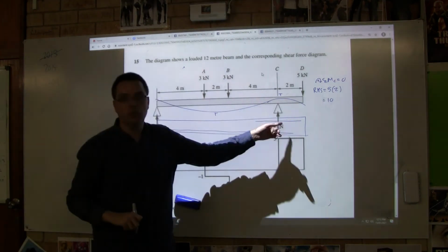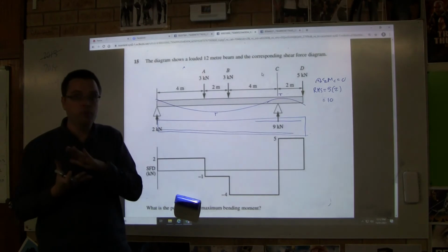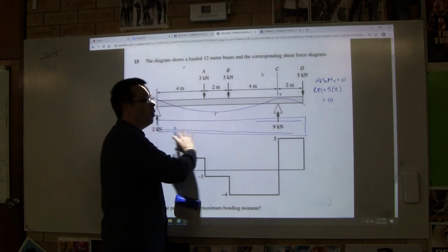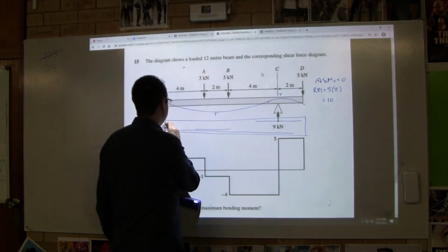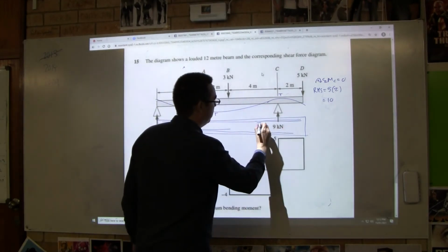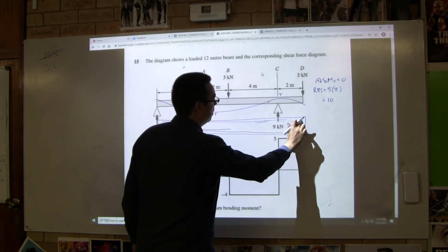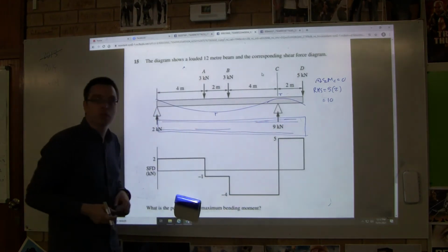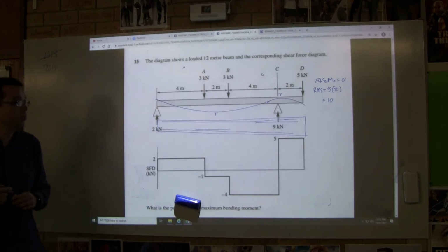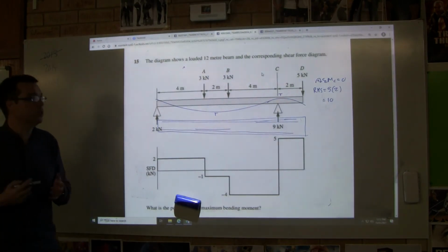So we put some steel there. Now, if we have a really small beam, we might actually put steel through the whole thing, but we'll put more steel there, and we'll put more steel there. We'll put extra steel there. If we had to squash the beam, if the beam has to be really little, you had to make it a bit stronger, put a bit more steel in there. So that's something we can do.